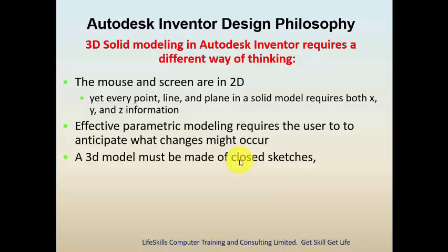After we make our part, we create 2 or more parts, we assemble them, we create what we call an assembly or sub-assembly. After we are finished with our assembly, you may want to create a presentation, that is an exploded view of your machine. After that, you go into 2D drawing, that is, you extract orthographic views from your 3D model. So that is the way we think in Inventor.